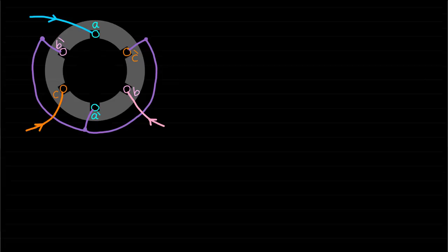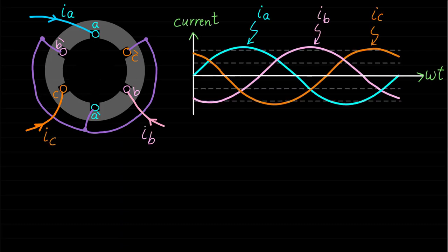It is very important to know that the three-phase armature windings of the synchronous machine carry three-phase AC currents. Note that we used concentrated windings here to simplify the drawing. However, we are still going to assume that the magnetic field distribution is close to a sinusoidal waveform. These three-phase AC currents are shifted from each other in time by 120 degrees in electrical angle.